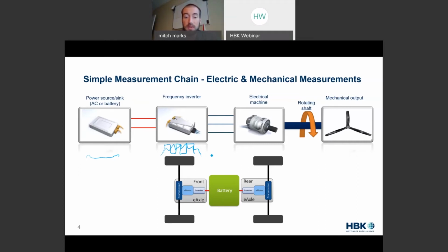This AC electrical signal is feeding an electric machine that's translating that electric signal into magnetics into rotation. But what we get is, when we have those pulses of voltage and current, we're getting pulses of magnetic, we're getting pulses of torque, and there's some filtering with the inertia, there's some electrical filtering, but at the end, in that mechanical output, we're going to have some torsional vibration just due to those switching effects of this multi-physics problem.